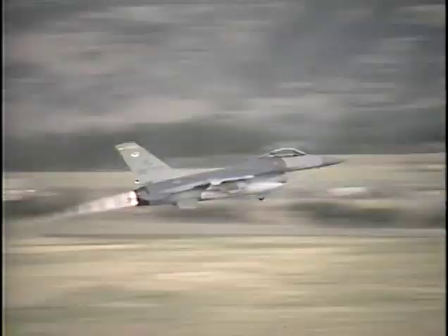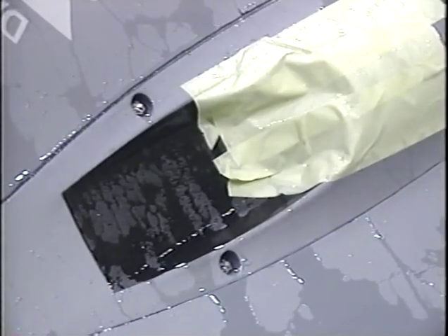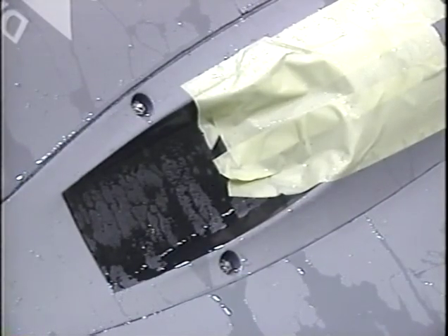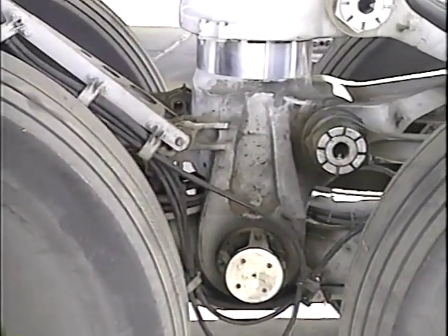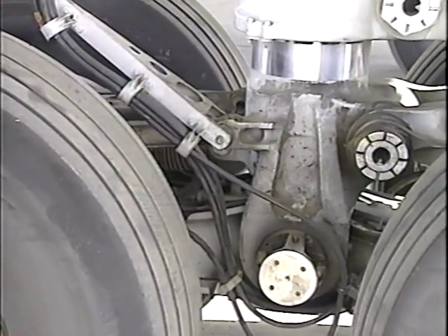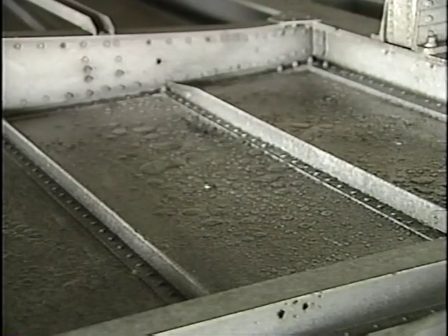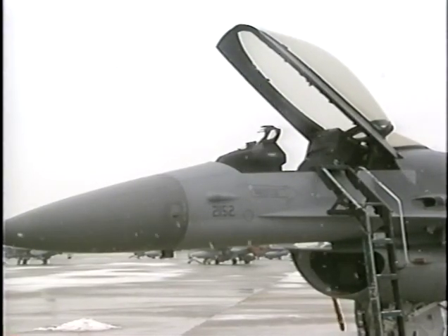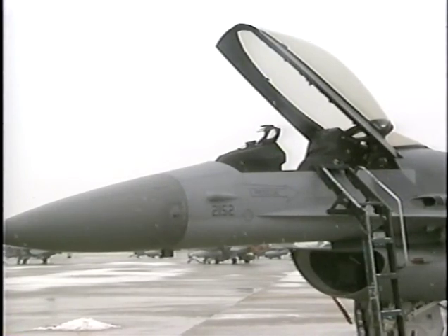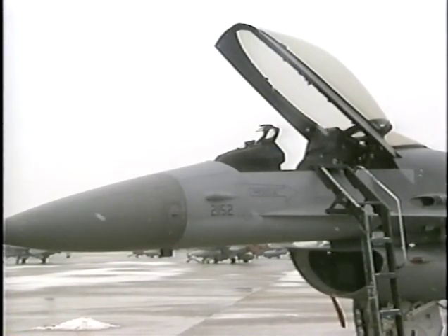Engine exhaust areas are often blistered by heat. Gun and missile exhaust surfaces are also blasted away by high-velocity gases and shell casings causing damage to the protective finish. In addition, these areas can become potential water traps. Wheel wells and landing gear assemblies are extremely susceptible to corrosion because of the elements they are exposed to. These areas are also vulnerable to water entrapment. Open flight stations and aircraft cargo bays are vulnerable to these elements when open to aircrew entry and cargo loading.